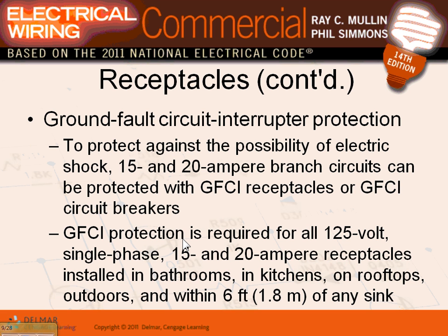So these are places where they added locker rooms in 2011. If you have a locker room, a sports facility with locker rooms with a shower area, these receptacles have to be GFCI. So there are a lot of applications for GFCI in a non-dwelling.